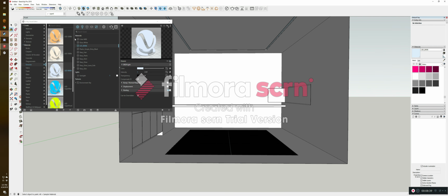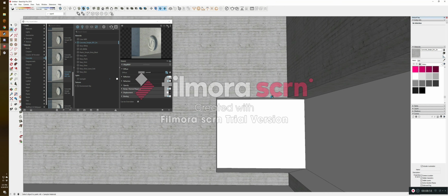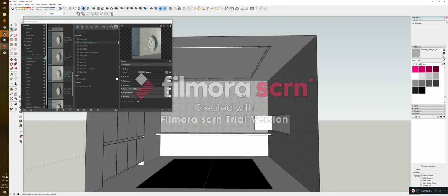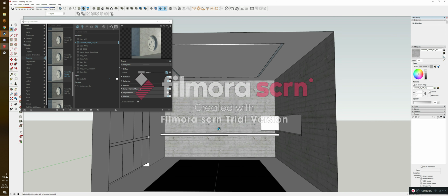For our exterior walls, I want those to be concrete, so we'll go grab some concrete. Let's do a simple patterned concrete like that. Okay, and it's too squished up and regimented, so let's make these a little bigger. Let's do 60 inches. Yeah, that looks good. Good. Okay.